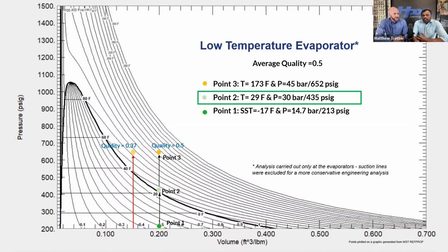So when you look at the analysis and also how it operates, now it becomes a constant volume. It's a fixed volume, right? So the volume doesn't change, but your temperature is going to change based on the heat gain. And then based on the temperature change, your pressure is going to increase.